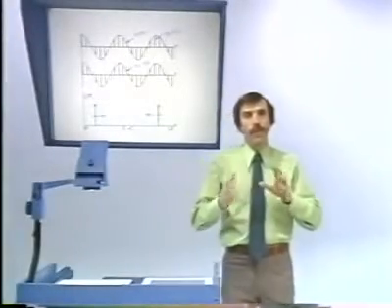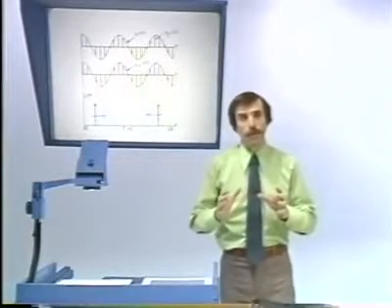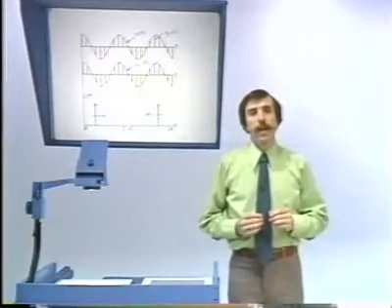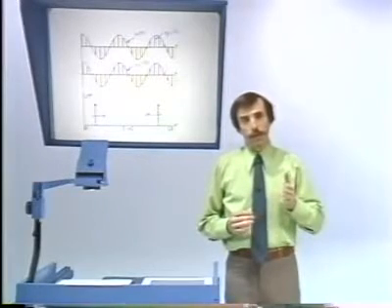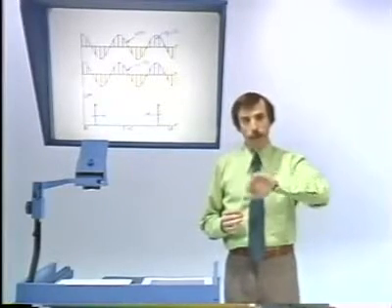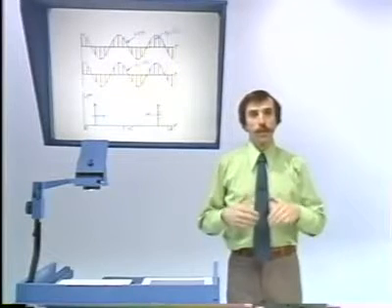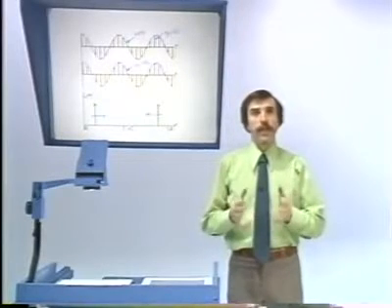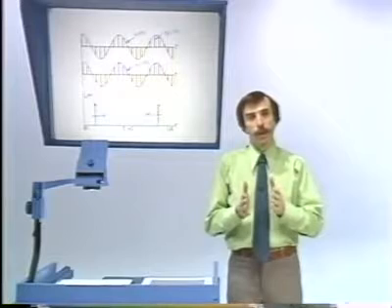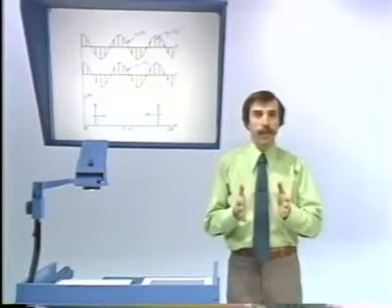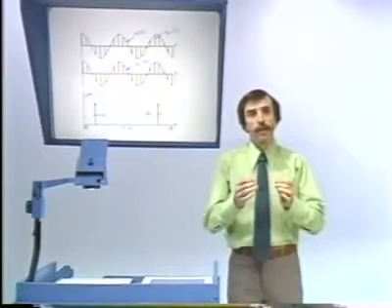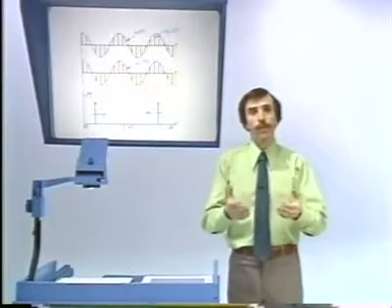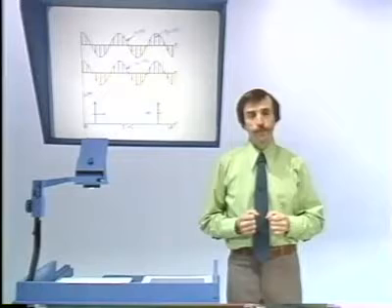So we've sampled a signal and then reconstructed the signal from the samples. And keep in mind that given a set of samples, there are lots of continuous curves that we can thread through the set of samples. The one that we've picked, of course, is the one consistent with the assumption about the signal bandwidth. In particular, we've reconstructed the signal whose spectrum falls within the passband of the filter.